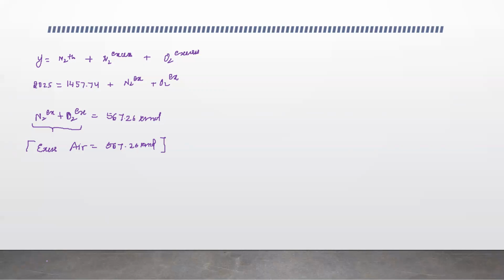Now, if you remember, in this video itself we did a problem where I discussed 6 formulas regarding excess air, percentage excess, right? One of the formulas was percentage excess is equal to excess air upon theoretical air into 100.